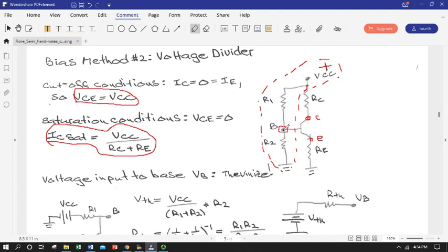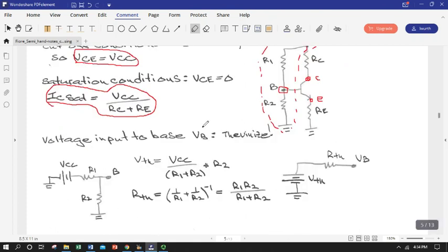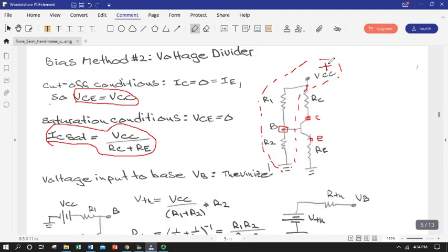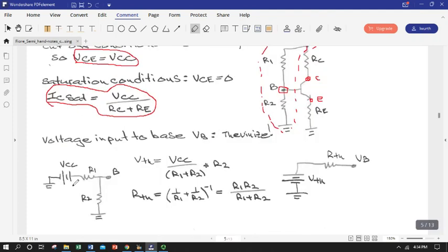In this case, it's the point of view of B, which is the base voltage, just so happens to be, because that's what we want it to be in the circuit. So here is a little reorg of what's in this dotted line, the dotted group over here, just written from the point of view of B. And so I'm going to put a dashed line around it so you know it's the same thing. Same part of the circuit, just written a little bit differently, so it's easier to see how we would Thevenize it.